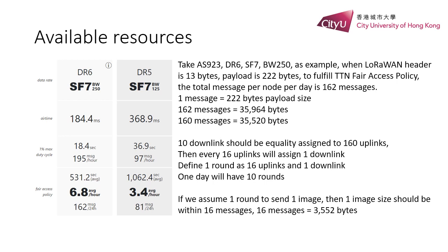If we take data rate 6, bandwidth 250, following the TTN policy, and send the maximum size payload LoRaWAN packets, we can send up to 162 packets per day. Each packet payload is 222 bytes.